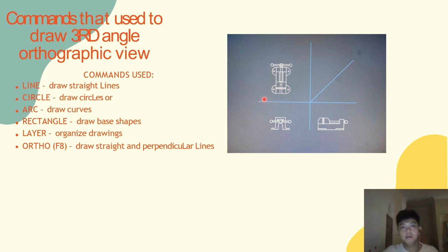Make sure that all the projections that you did are correct so that you can start the front view. For the front view, you draw a straight line from the bottom and find the dimension for this one. And also you just put it upward and do it like a box first, and then you just trim.